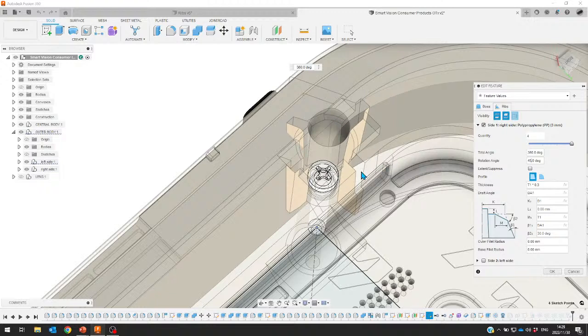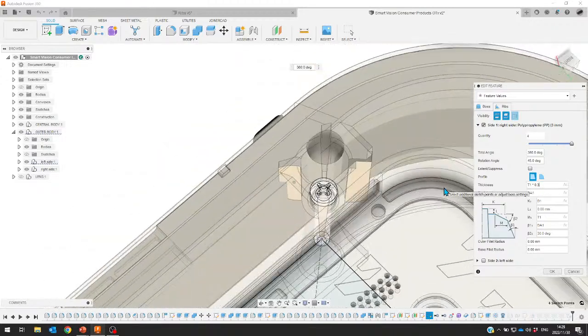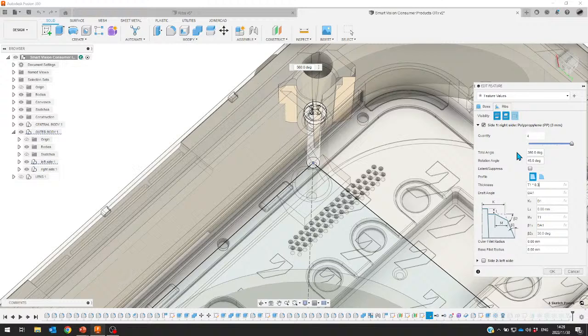And we'll see the orientation of those ribs rotates accordingly. So there they've rotated 45 degrees. And same as with the boss itself, you can go through the list, you can update the values as needed. And then when executing that, that geometry will be created. So quite easily here, I can add those ribs onto the bosses.